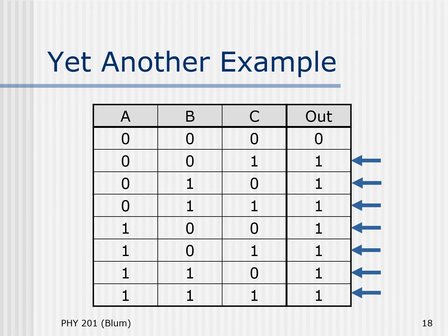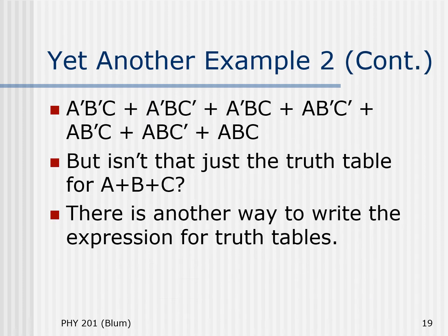Next, I want to show you that you can always take this approach, though it might not always be the best approach. So let's imagine the following example, where the truth table has a 0 for that first row. So A, B, C, all zeros gives a 0, and all other rows give 1. So now we have 7 terms to write. So we can pursue our sum of product approach.